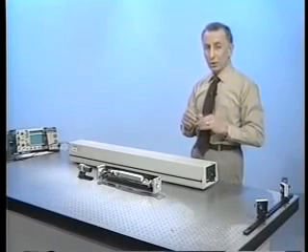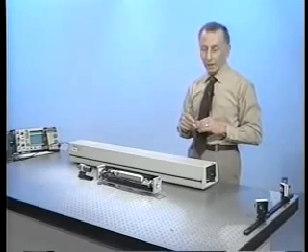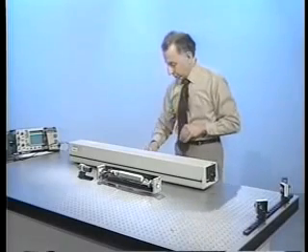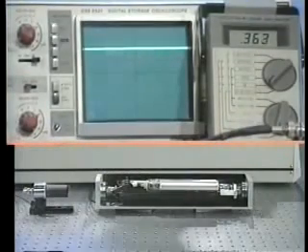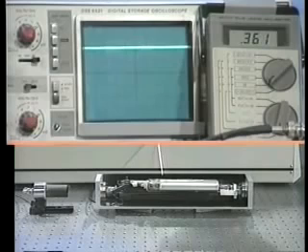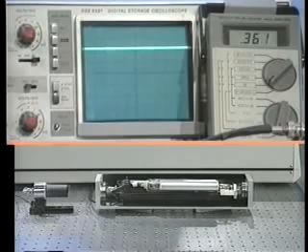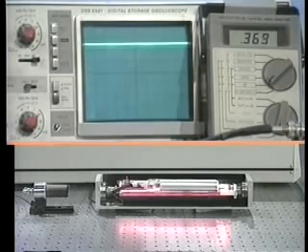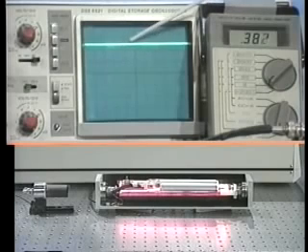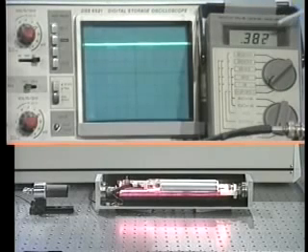Now we come to this crucial demonstration of gain. So now I want you to watch both the scope and the meter as I turn on the amplifier. So here I'm going to now turn on the amplifier. And remember, this number is around 363 or so, 364. Now you can see on the scope we jumped a little bit, and the meter has gone up to 380 something, which is an increase of about 5%.